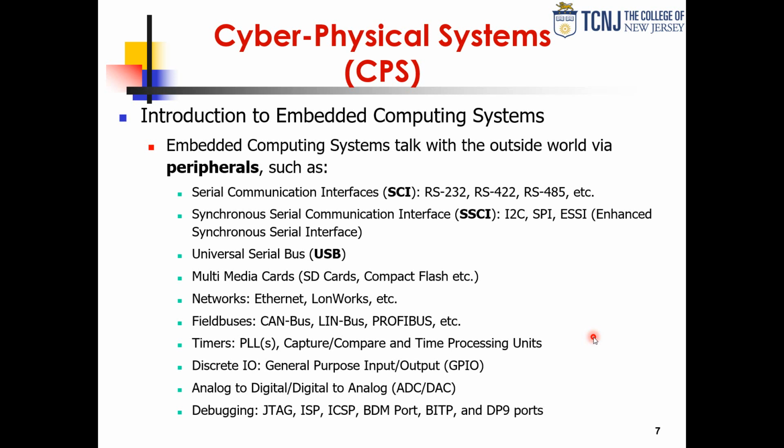But as more electronics were added to cars, we were putting too many things on that CAN bus, and the primary priority was safety. So the LIN bus was evolved to basically put in that LIN bus all the lower tier things. So the things that are going to be in the LIN bus are your mirrors, your defoggers, things like that. Each one of those is still going to have a processor actuating those actors in the system. Then we have Profibus, this process field bus, widely used in processing, pharmaceutical processing, and things of that nature.